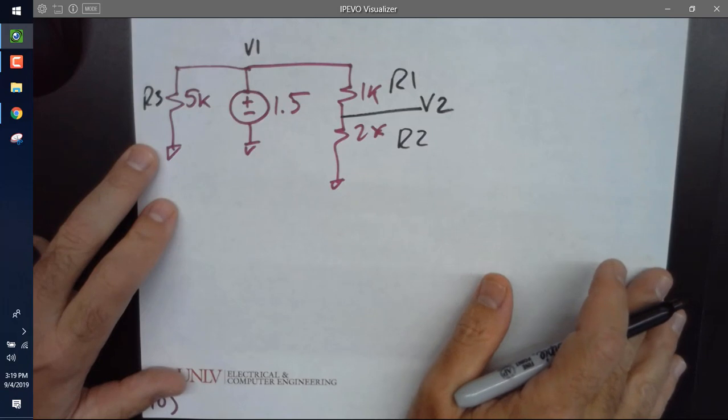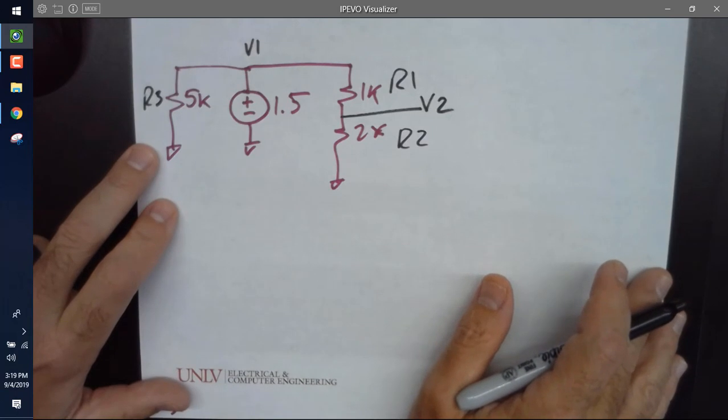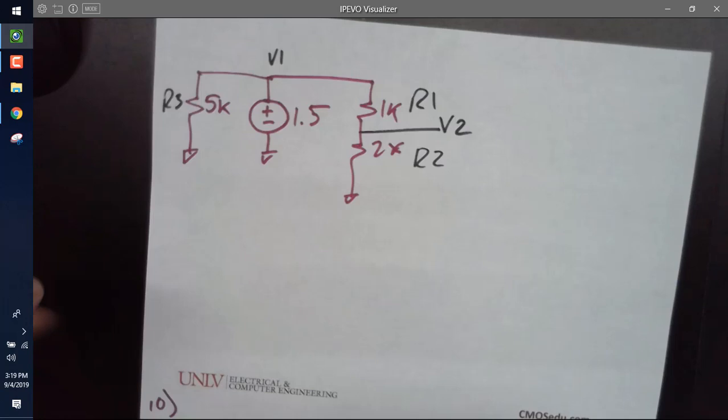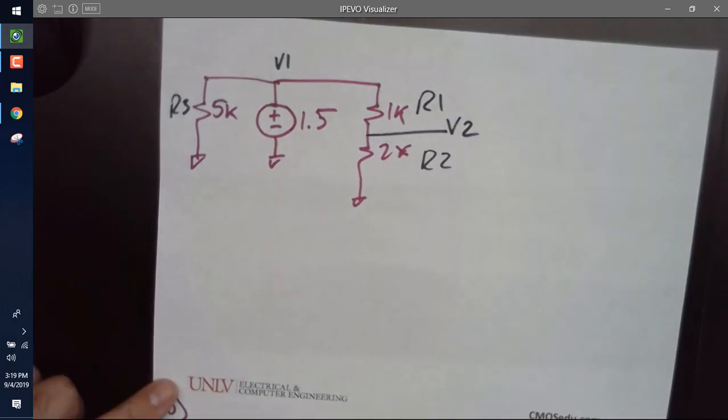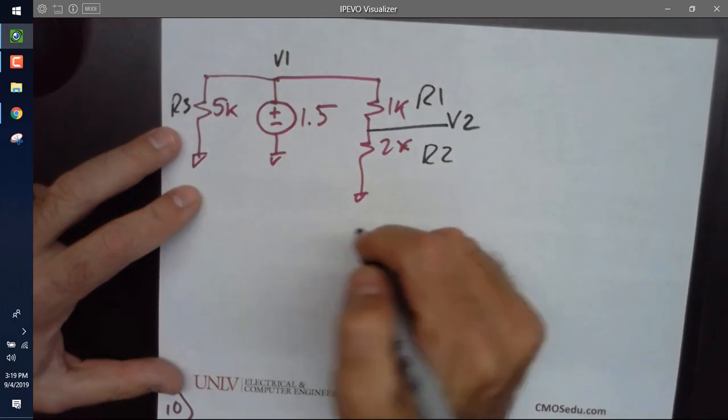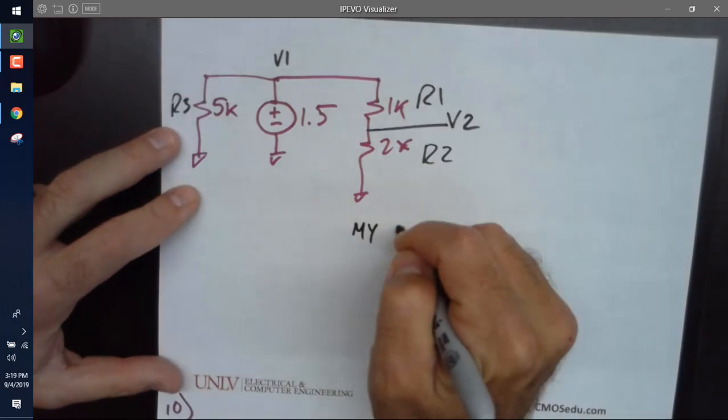One thing you need to remember when you write a net list: the simulator ignores the first line, and that can be really irritating if you don't remember and you're doing something manually and sending it to a tool, thinking it's looking at the first line. It ignores the first line. So I'm going to put in, for this, my net list as the first line.